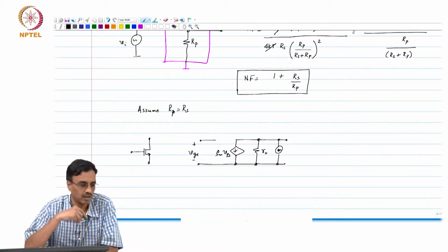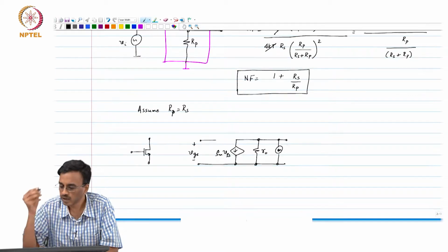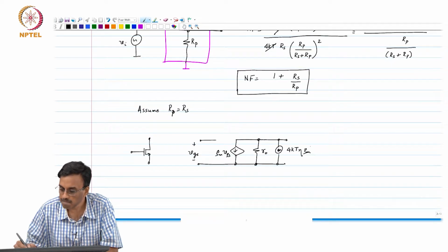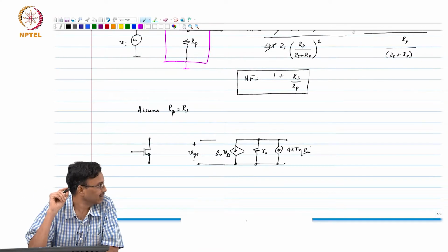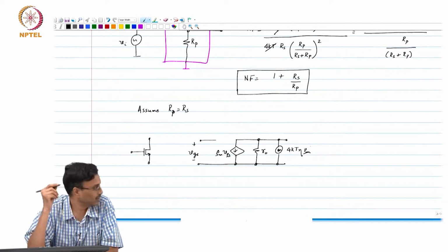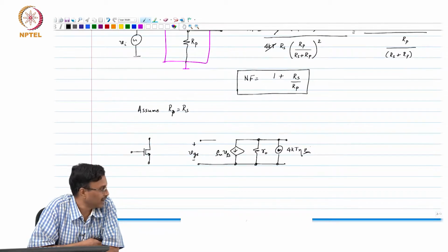But then long channel MOS transistors only exist in the textbooks. So a better formula is to use 4kT eta times gm, where eta is some number that fits measurements, eta or gamma or whatever they are; that is the usual non-ideality factor.